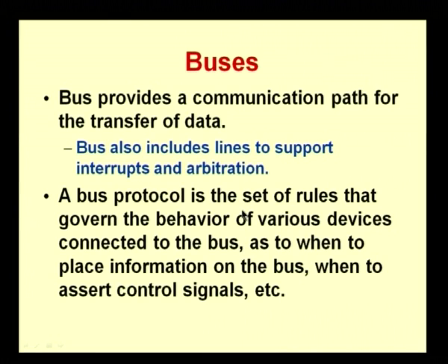A bus protocol is something that we also have, which is a set of rules that governs the behavior of various devices connected to the bus as to when to place information on the bus, when to assert control signals and so on. When the data can be placed on the bus, when the data can be taken from the bus, all these things are controlled by means of a bus protocol. So, whenever we have any bus that is designed, we would normally have a protocol that goes with it, which we need to understand to see how exactly data will be transferred from the bus and to the bus.